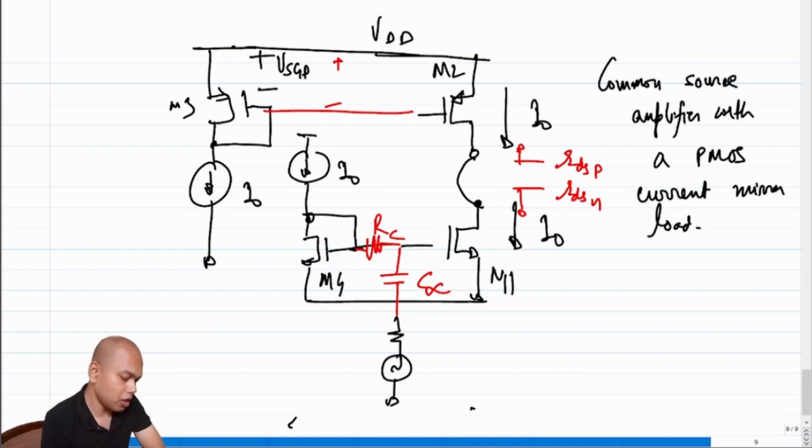This load is not a physical resistor. The incremental loading that M2 is providing is through a p-MOS. It's an active device, because it requires a VDD to get biased properly. So this is also often called an active load.